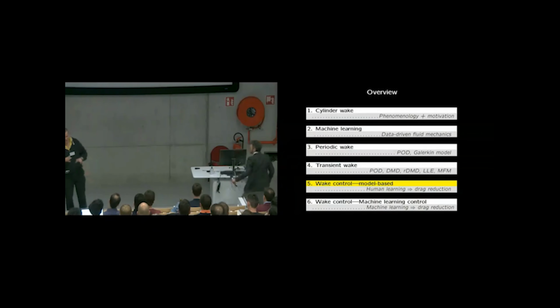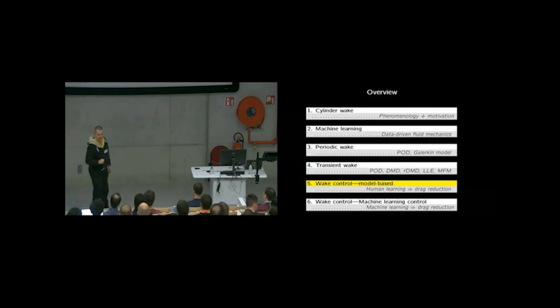And now the question is, how do you incorporate the pressure term? Now there are many possibilities. And you have alluded to one, namely you do the POD of the pressure field, and you put the pressure field in the Navier-Stokes equations, and you have one system of equations for the POD mode amplitudes for the velocity field, and you solve the other coefficients with the pressure Poisson equation. This is one possibility. Another possibility, actually, you can derive an accurate pressure term representation for the POD modes. This is what we did in 2005 in a JFM paper.